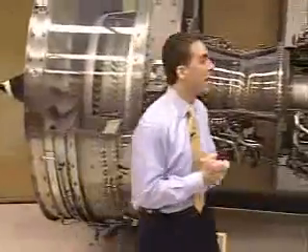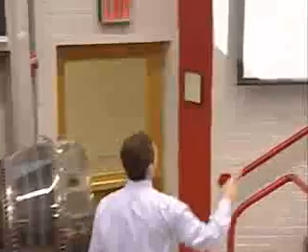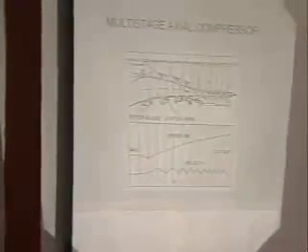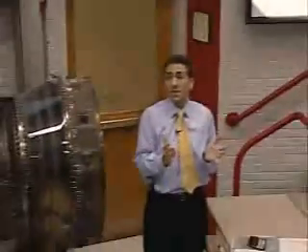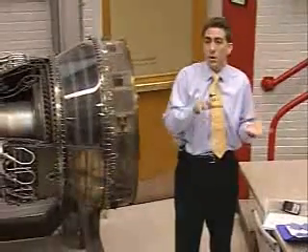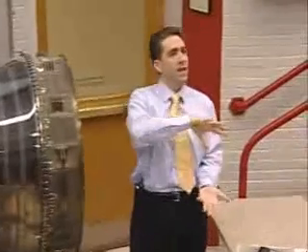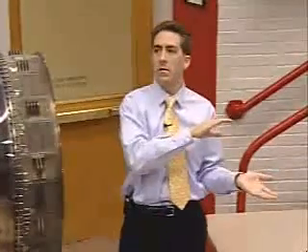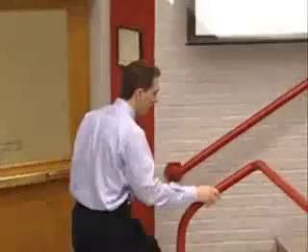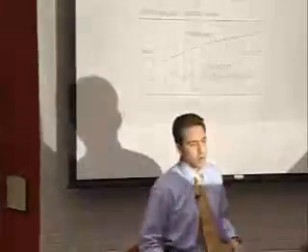I could have 18 or 20 in a machine like this, and each time you're keeping the velocity pretty constant so that the axial component of kinetic energy through the machine is about the same. But you keep adding swirling components, convert that into internal. Add some more swirl, convert it to internal. Right? So let me put a few more words around that.